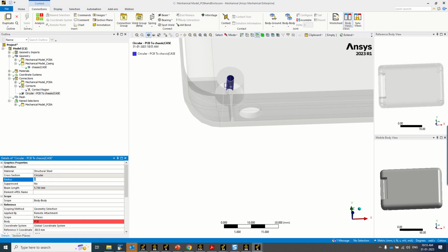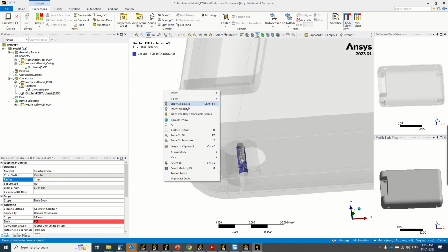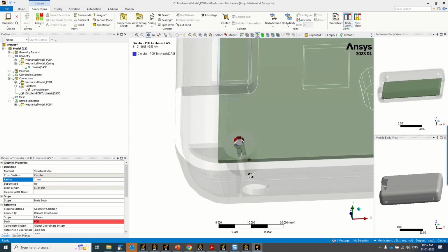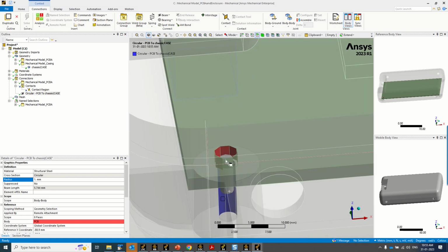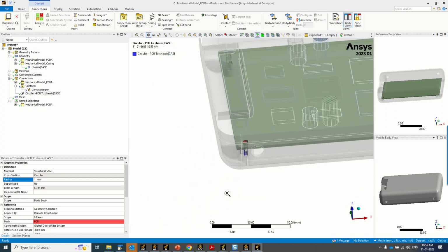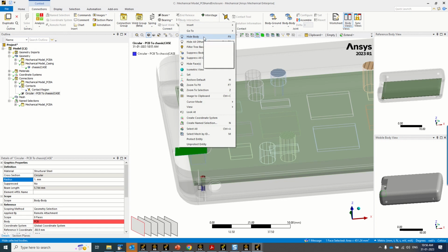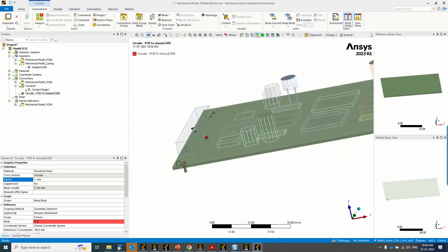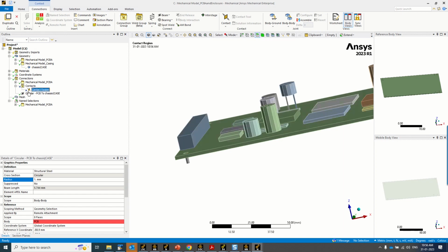Okay, and this is going to have a radius of 1 mm. So now we can see a new screw type of connection get created here. All bodies. So this screw is going to connect this hole and the bottom hole. Clear? So now we did this for one of the screw locations. Now we need to do this for 3 more locations.